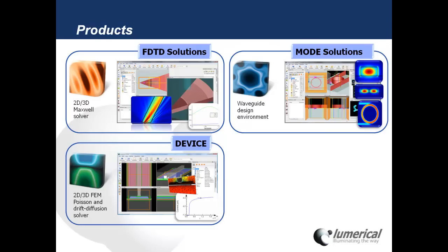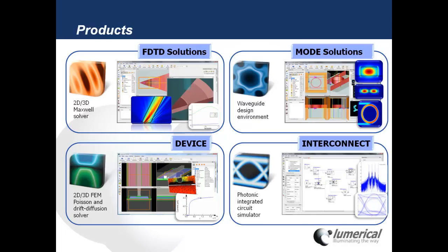Device is a 2D and 3D finite element Poisson and drift diffusion solver, which allows you to solve for the electrical properties of devices, and we typically use it for optoelectronic devices in conjunction with FDTD Solutions and Mode Solutions. And then INTERCONNECT is our photonic integrated circuit simulator, which allows you to simulate large-scale photonic circuits at a higher level of abstraction in a way that's more similar to SPICE modeling in electronics.